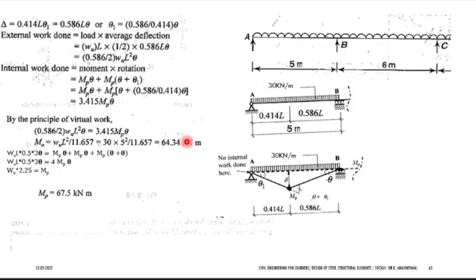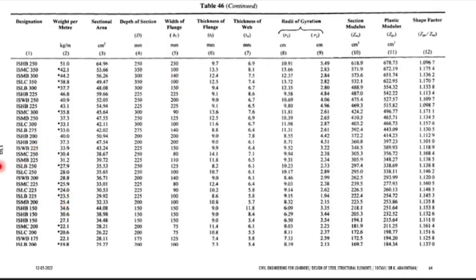Now what is the highest plastic moment in these 3 spans? At the span BC you got 67.5, and for this plastic moment you have to check whether the section is safe or not. How can you check that? You can check by using the code book. Take the annexure H. Now you have at page number 139. Take page number 139. From 138 you have the section criteria.